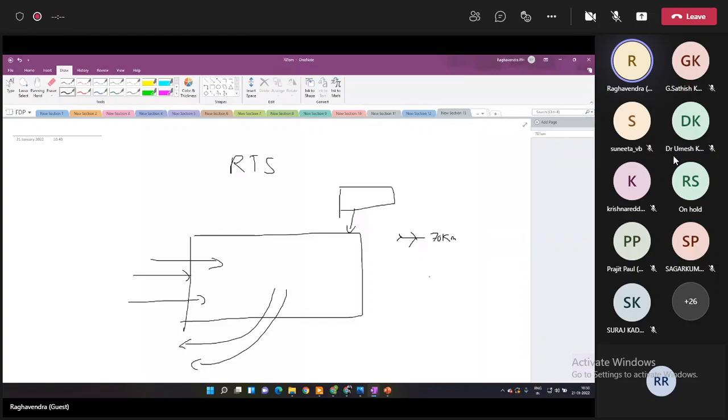And there is a concept called radar cross section. When you send out a radar pulse, depending on the area and the shape of whatever is there on the plane, a certain amount of signal is reflected back. The area that reflects back the signal and the power of the signal reflected back, all of these are factored in, and it is given as a term called radar cross section. We call it RCS.